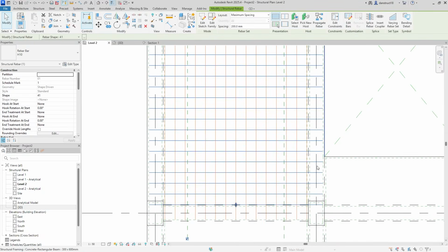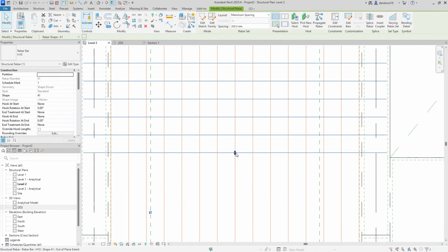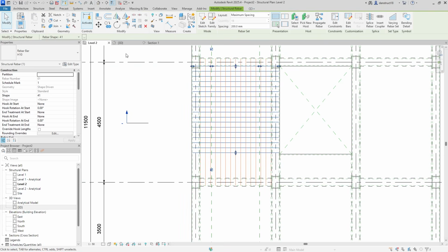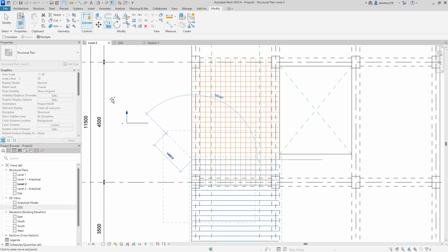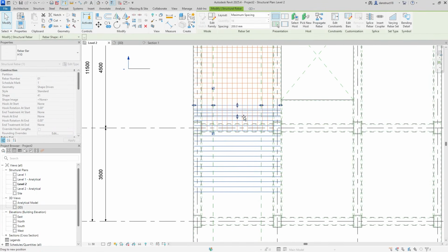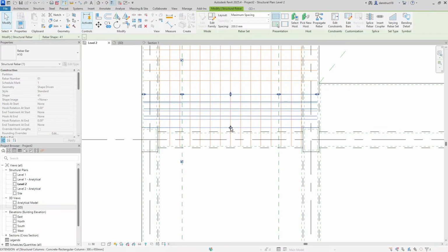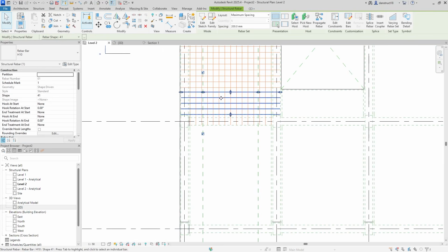So we want it to extend to the other slab. That's a continuous slab. So I'm going to drag this part up a bit. The reason why is because we have a segment that anchors on both ends. So we're just going to go ahead and copy another one downwards like this. Click on modify. Now click on this and drag the grip points all the way back into this panel. There we go. Great. And just drag it up a bit. There we go. Good. All right.